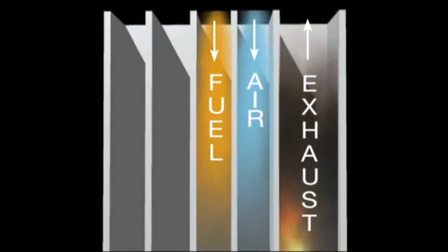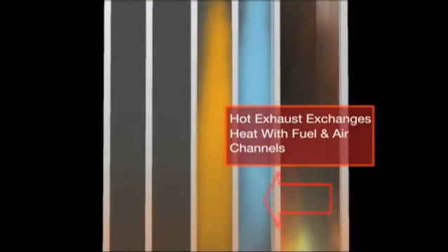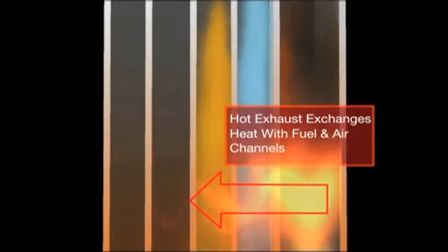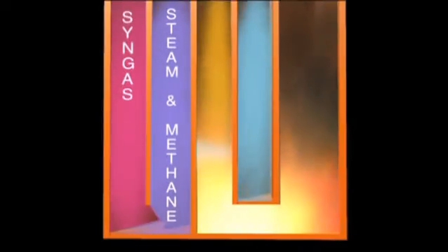Temperature increases rapidly, moving toward the bottom of the reactor block. Air and fuel mix at the hot end and combust catalytically. This method of combustion minimizes unwanted byproducts, including oxides of nitrogen, commonly referred to as NOx. The exhaust stream makes a U-turn and exits at the top of the reactor.